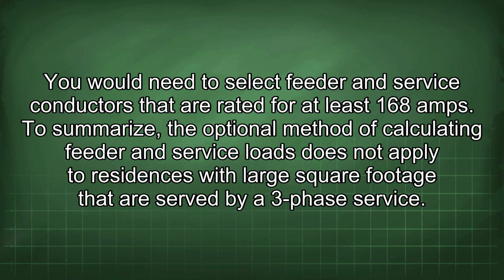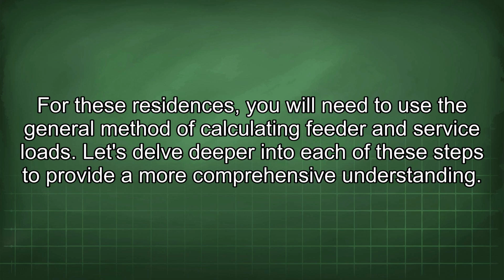To summarize, the optional method of calculating feeder and service loads does not apply to residences with large square footage that are served by a 3-phase service. For these residences, you will need to use the general method of calculating feeder and service loads. Let's delve deeper into each of these steps to provide a more comprehensive understanding.